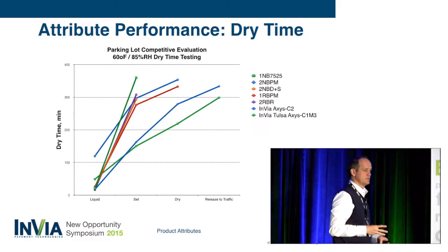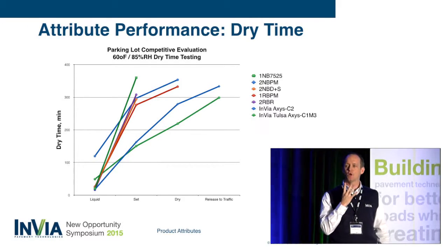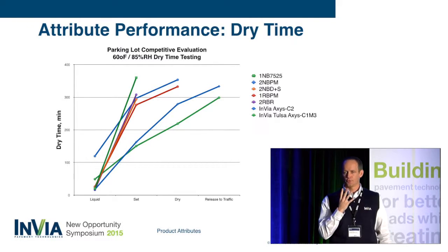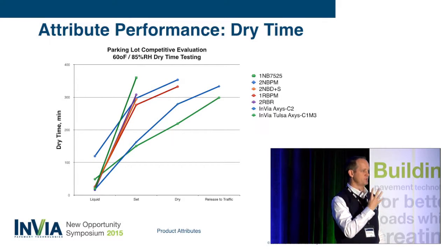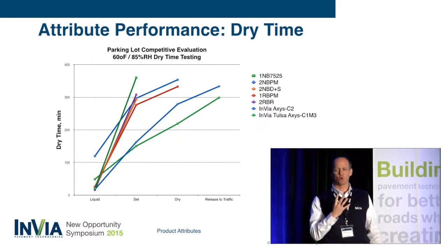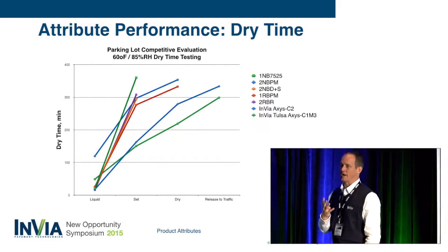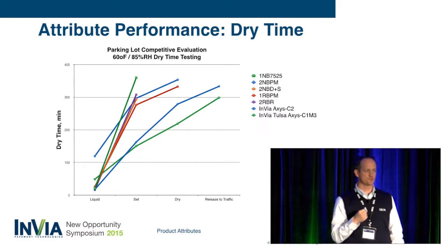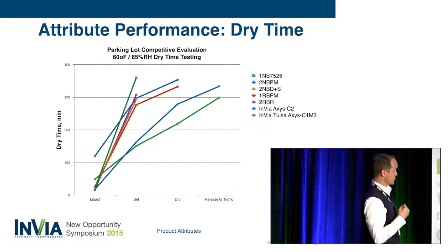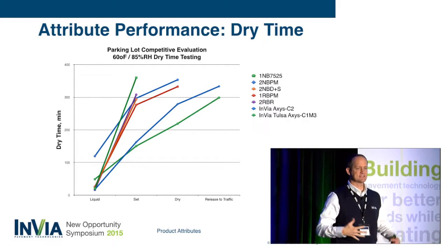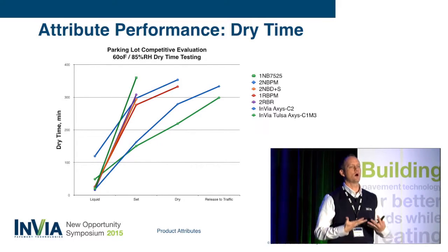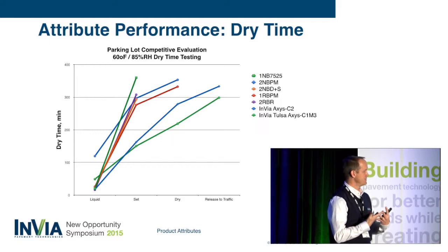Wind speed and relative humidity. If you know those 4 variables, you can plug them into the equation and you can know to the minute how fast a puddle of water of any given size is going to dry. And so the race to drying fast and curing as well is how fast that system can move the water out into the surface to be wicked away.